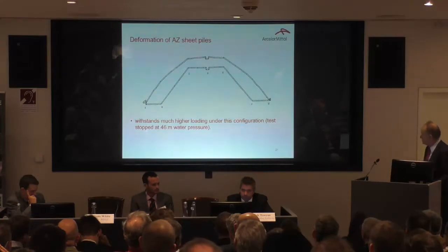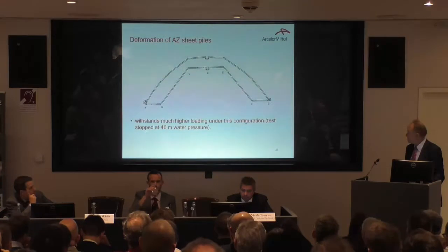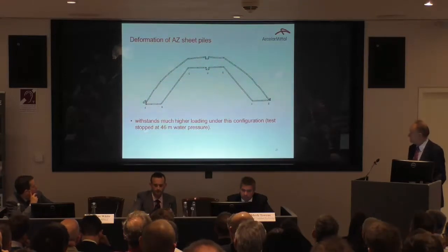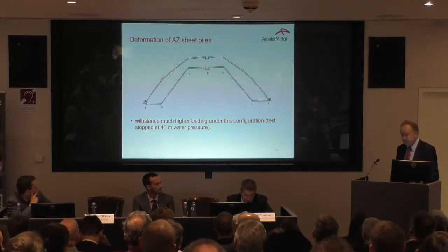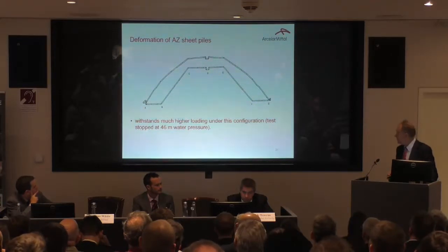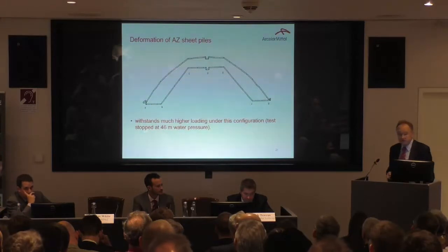So we can use this in the design of our walls, especially in combi walls, by using the lighter range of the Zs under loads of 30 to 50 MPa. You can get some flexibility, allowing some energy absorption before rupture or splitting of the interlock itself.